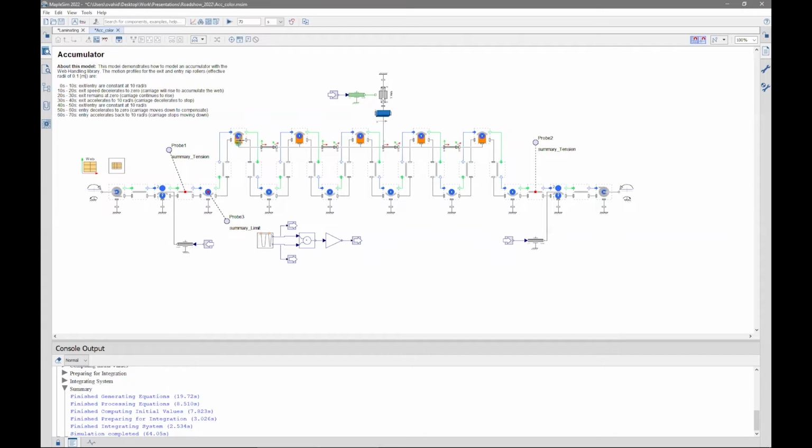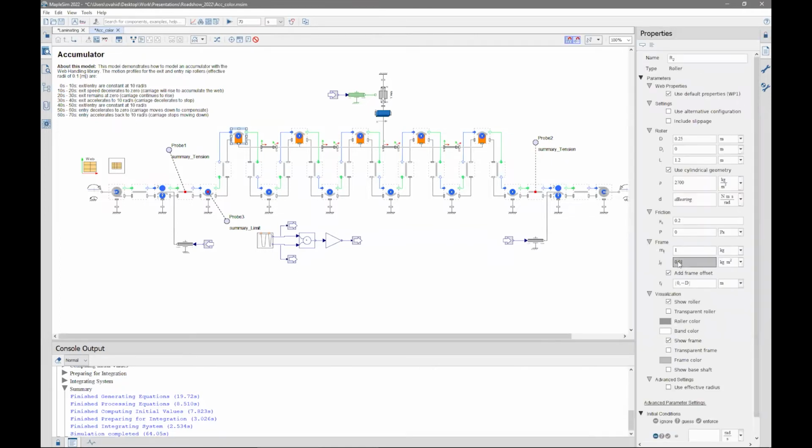Similar to the arms for that pivot, we have components, or the rollers, that have offset activated. As you can see, in a typical roller component, we have the inner diameter, the outer diameter, and length, and we can have MapleSim estimate the inertia for the roll based on its density, or we can not use the approximation or estimate and provide the exact inertia from our actual design.